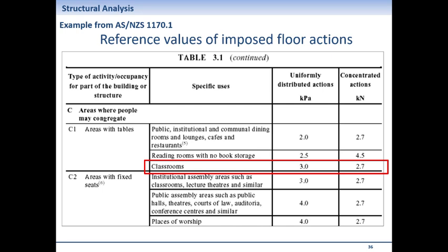3,000 newtons. That translates to approximately 300 kilos. An average person about 70 kilos, let's say 75. That becomes how many people? 75 times 2, 150, times another 2, 300, yes? So in 1 square meter, the live load that it is recommending to use is approximately 4 people in each square meter. So it's pretty dense. 4 people standing next to one another.